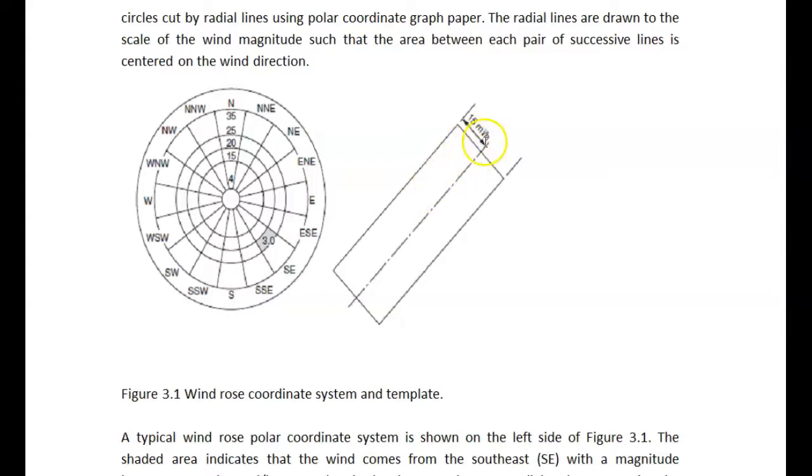So we are trying to ensure that the crosswind component does not exceed 15 miles per hour. So we pick this template and superimpose it on here in such a way that the center line, which represents the center of the runway, matches here, and from there we can rotate it. We can move it this way or this way. As we continue to move it, we check, because this template will be able to cover from here, this direction, to here.